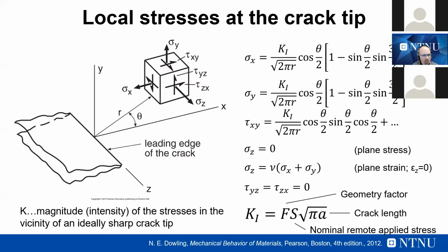And a question is, do we have plasticity close to the crack tip? The answer is usually yes, we have a small volume of plastic material close to the crack tip, but this plastic volume is actually much smaller than the process zone where the K1 factor, the stress intensity factor, is leading the phenomenon. And so we can still use the approximation of linear elastic fracture mechanics.